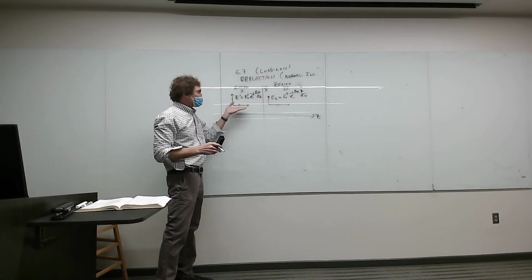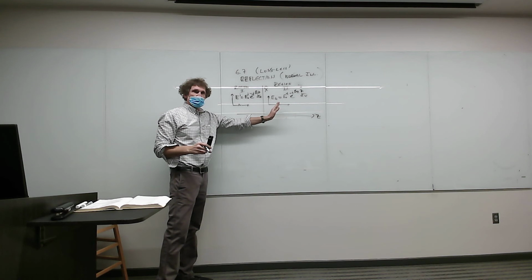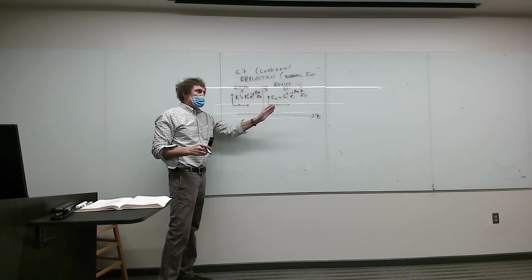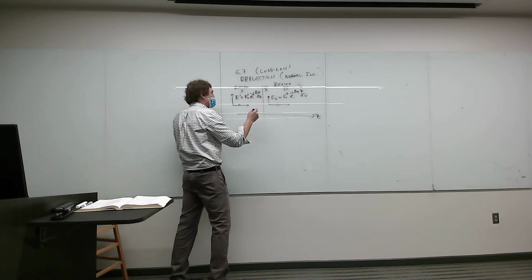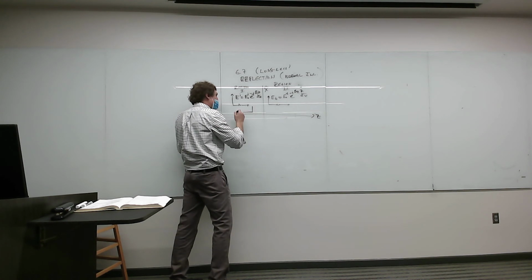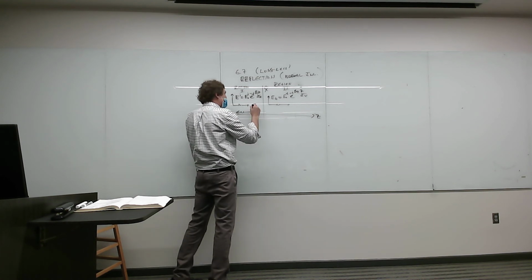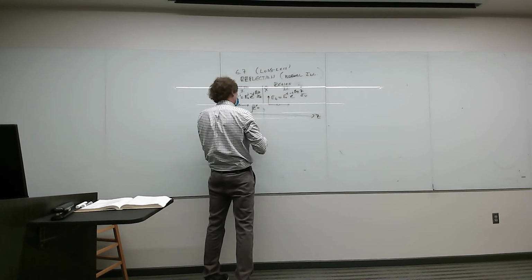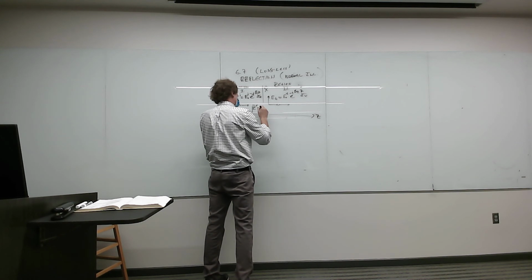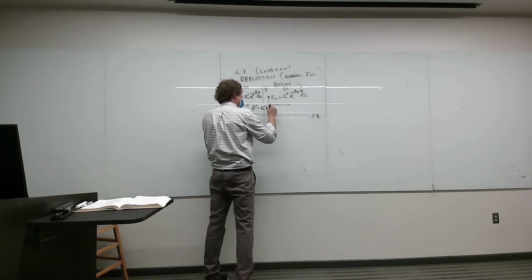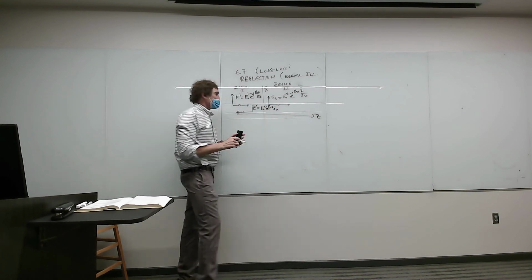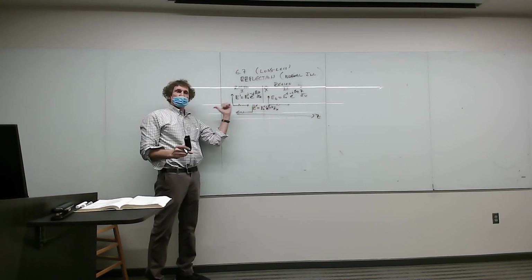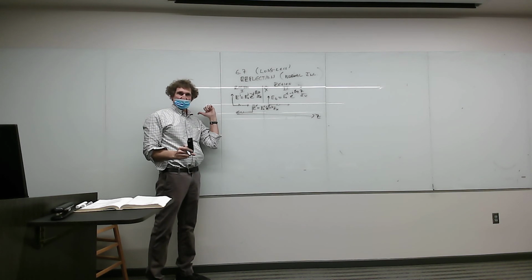All right, so the wave comes, hits, some of it's transmitted. This should make sense to everybody, right? We don't know how much it's transmitted, and some of it's reflected. So when we have a reflected wave, we're going to have an electric field reflected, and that's equal to E naught reflected e to the plus j beta 1 z ax. The reason it's plus j beta 1 is that it's going in the negative direction. Okay?